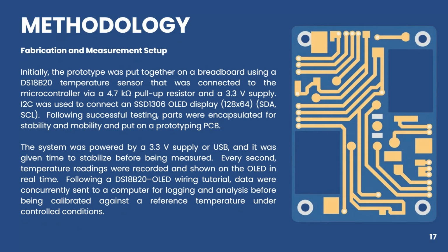For the fabrication and measurement setup under this methodology, initially the prototype was put together on a breadboard using a DS18B20 temperature sensor connected to the microcontroller via a 4.7 kilo-ohm pull-up resistor and a 3.3 volt supply. I2C was used to connect an SSD1306 OLED display, which is 128 x 64, with SDA and SCL.